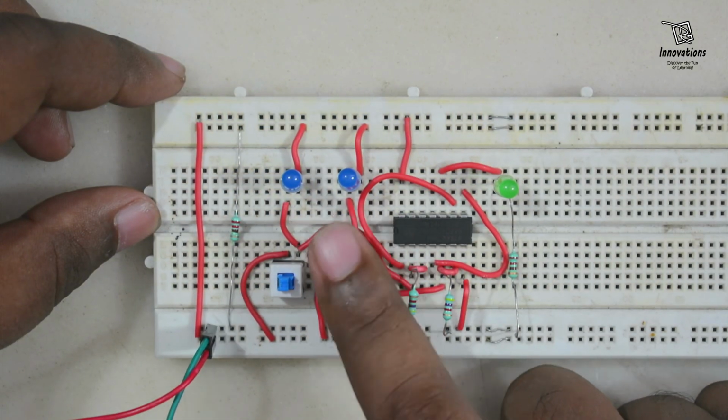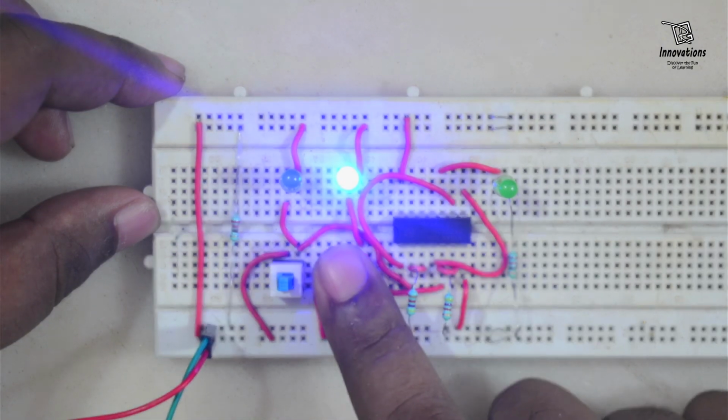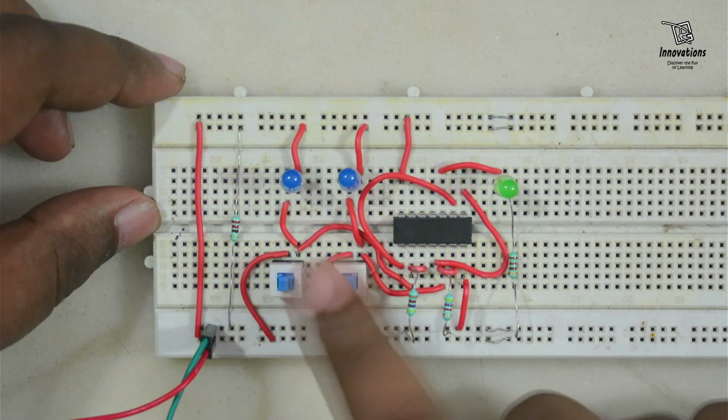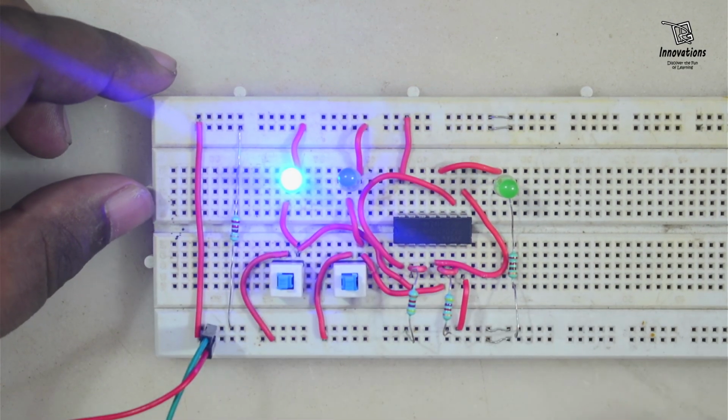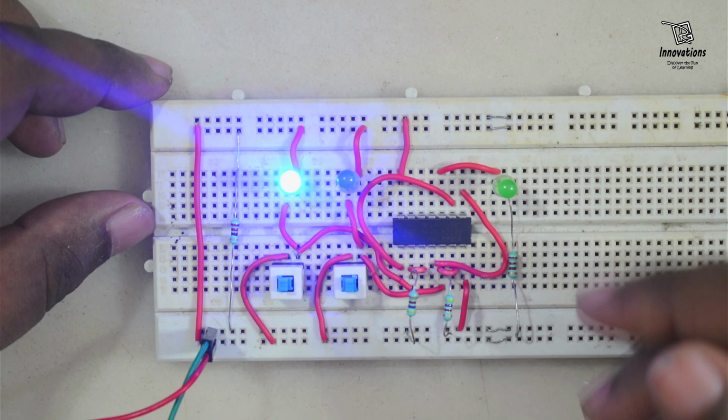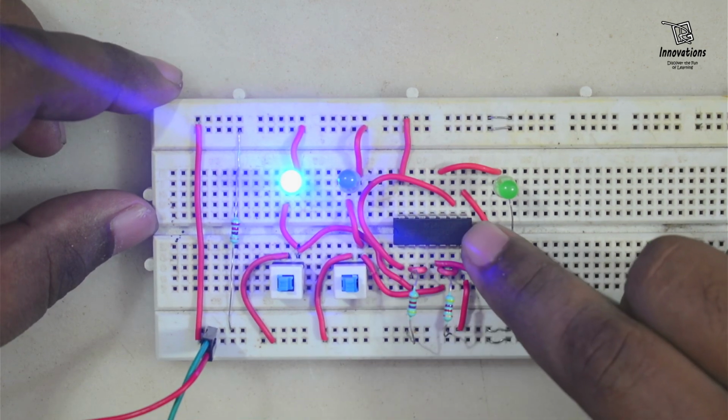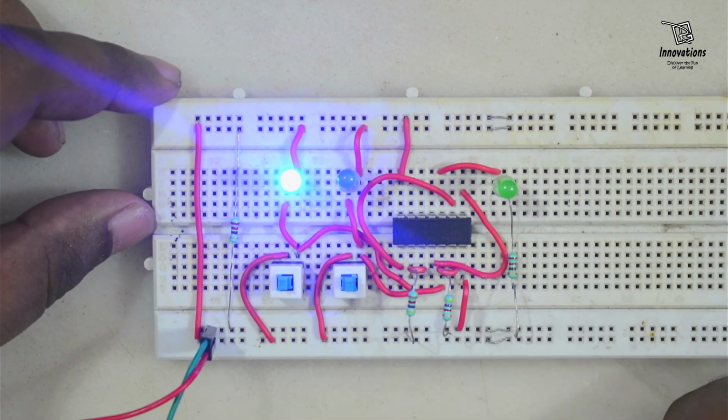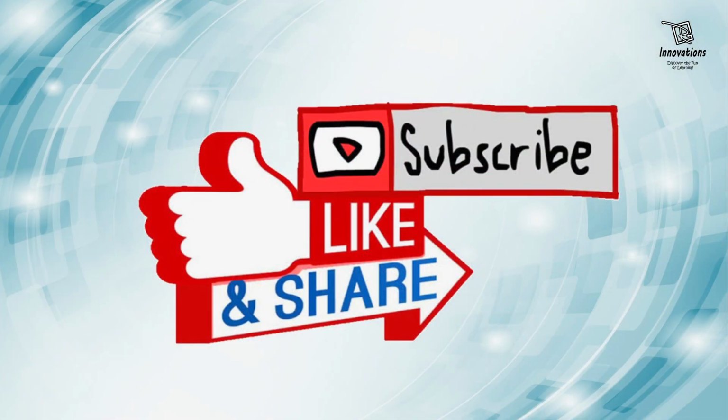When both inputs are 0, output is 0. When any single input is 0, output is 0. So this satisfies the truth table of a 2 input AND gate. So now we have seen how we can convert a NOR gate to a NOT gate, OR gate and AND gate. So that was the practical demo of a NOR gate as a universal gate and converting the NOR gate to the other basic gates. If you have any confusion, please feel free to ask in the comments.